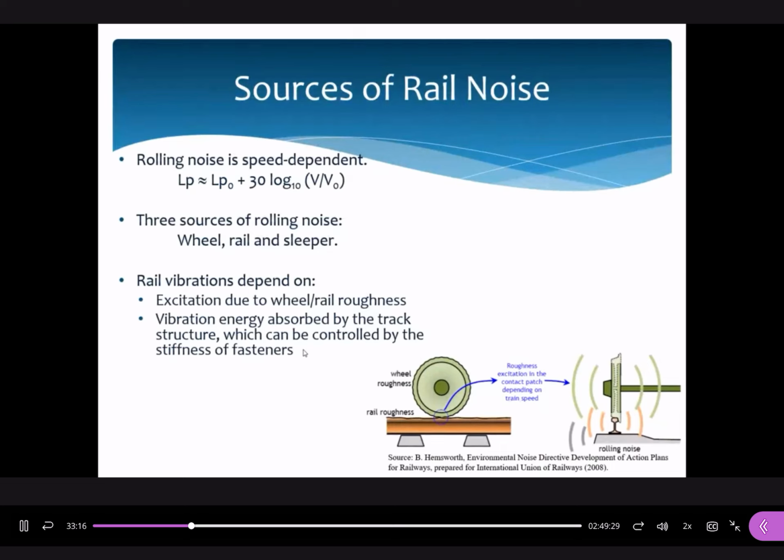So here I just want to introduce these equations to you. How to do calculations I will introduce in the next lecture. In this one, how to read this figure? We want to reduce the transmission of the force that can be transmitted through the structures to the surrounding environments, so that transmission of force can be reduced at higher force frequency. A broader frequency range of vibrations can be isolated by lowering the natural frequency of the system.